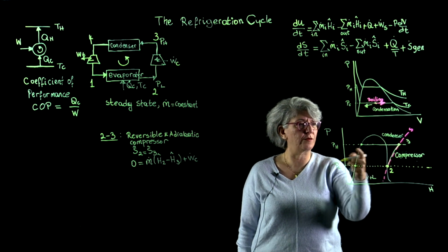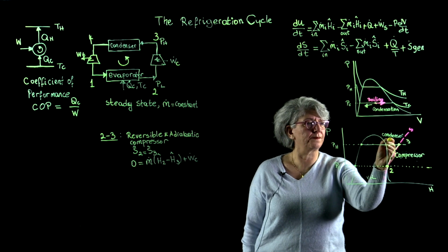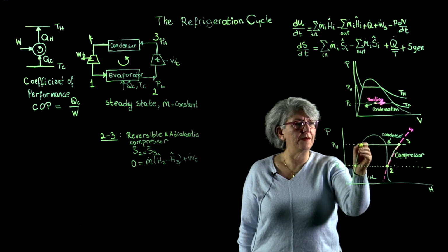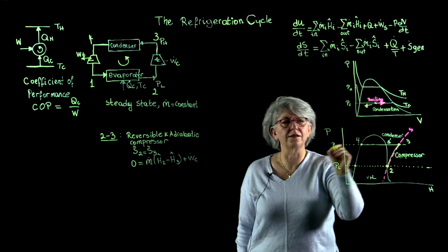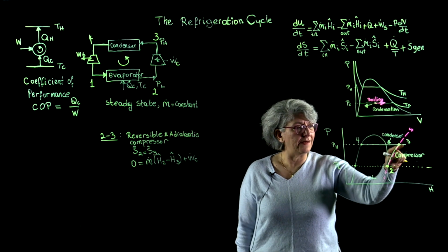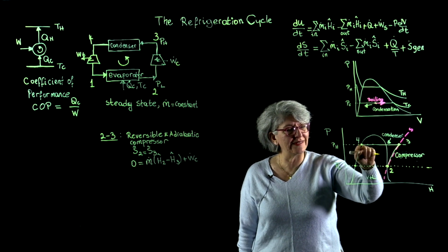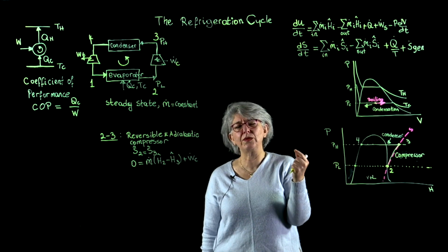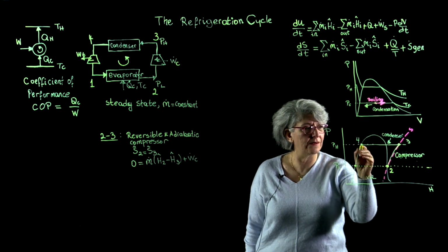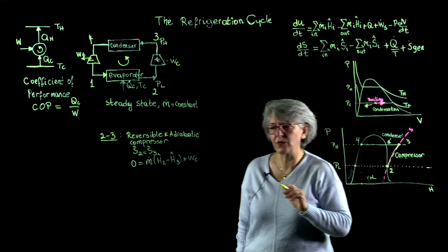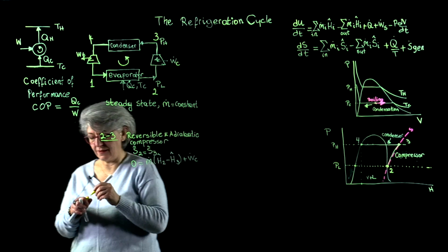This line corresponds to the condenser. All right. And I'm now at state 4. Now, given that I know the pressure and given that I know that this is a saturated liquid, allows me to determine all the state variables with which I can calculate the enthalpy.